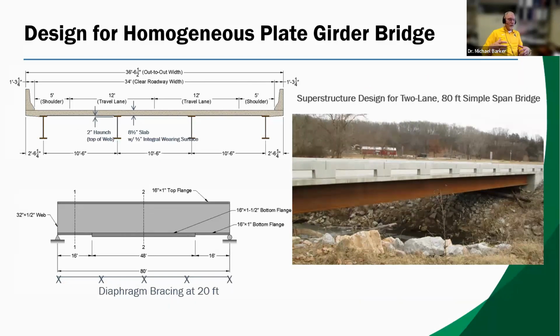eSpan 140 gives us a preliminary design that says, this is close to what should work. And what it told us was 4 girders at 10'6", and it's got the deck up there, and there's our elevation of our girder. And now we can go into a final design type process.